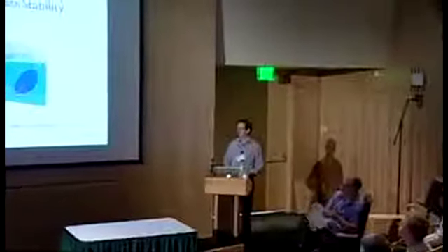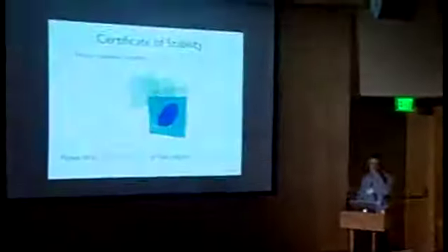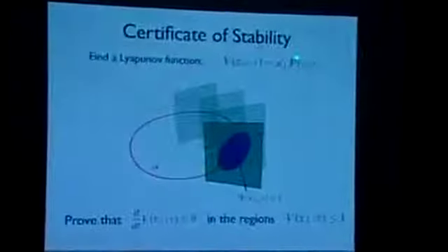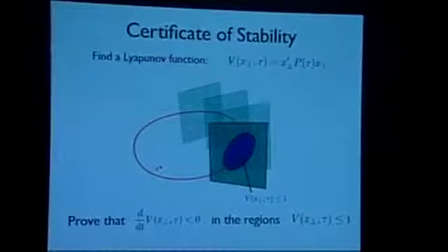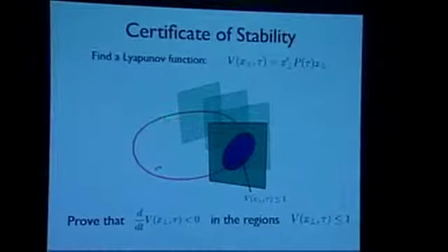Okay, so how do we certify stability over a region? What we're going to look for, and Anton hinted at this before as well, is a Lyapunov function candidate, which is defined in X-perp but depends on tau. So it could be quadratic. It doesn't have to be quadratic, but the simplest classes of functions to search over are quadratic. What I've illustrated here is a nominal cycle, and this doesn't have any impacts, but this is just an illustration, and a bunch of these transversal surfaces around it.